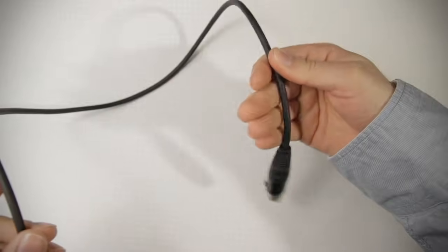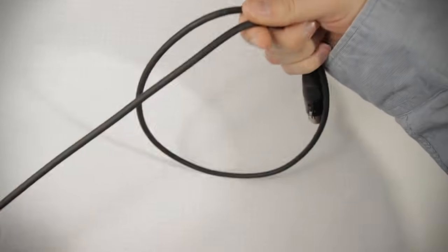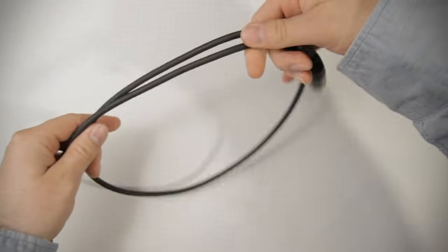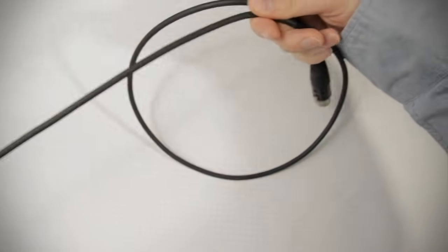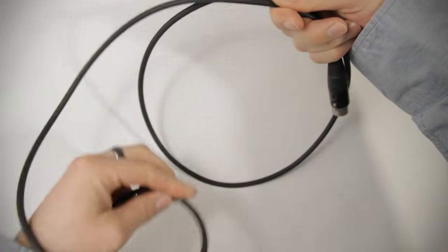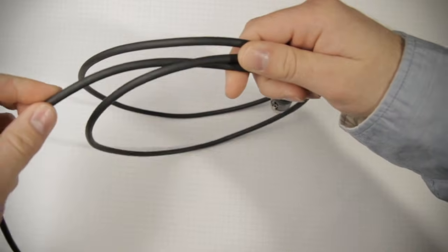Now you may hear this technique referred to by some different names. One is twist, reverse twist. One is the studio wrap. One is over under. This is what it looks like. Hold one end of the cable in one hand, and then you're going to make a loop here. Now the first loop should look like this, where the long part of the cable is on the outside. Then the next loop, you're going to take your other hand, in my case the left hand, and you're going to make kind of a half twist on the cable so that it goes underneath the line.